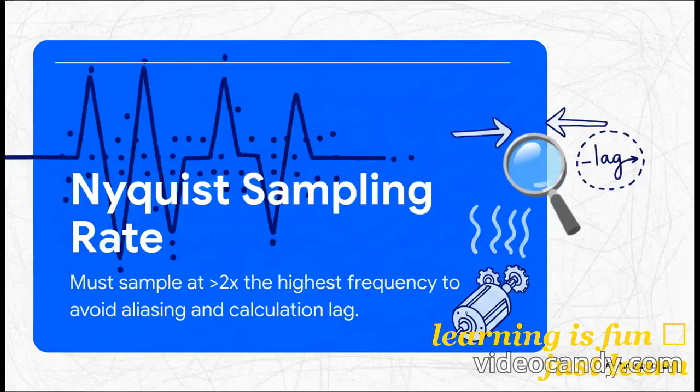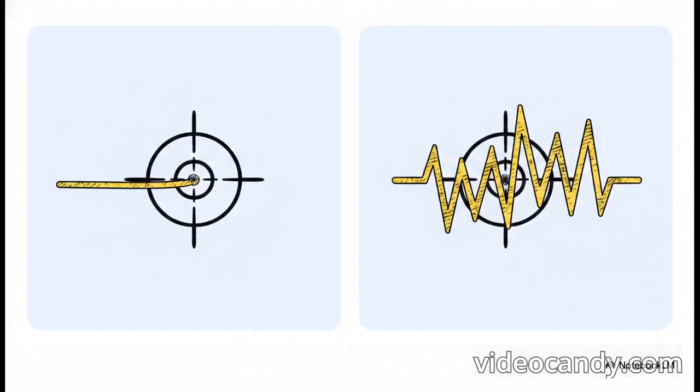But here is exactly where we hit a massive physical wall. When we execute a discrete proportional integral, or PI calculation, in that current loop, we immediately face the fundamental sampling theorem. To avoid aliasing, which is basically when your system generates false phantom signals, a measuring device must sample an analog signal at a rate more than twice its highest frequency. That's the Nyquist limit. But taking those samples and crunching the math takes time. This inherent calculation dead time delay, also known as transport lag, physically prevents the system from instantly suppressing high-speed mechanical disturbances. This creates a classic agonizing dilemma for control engineers.